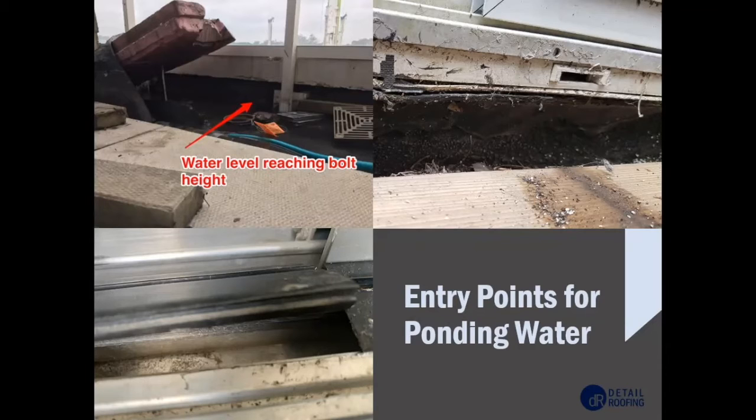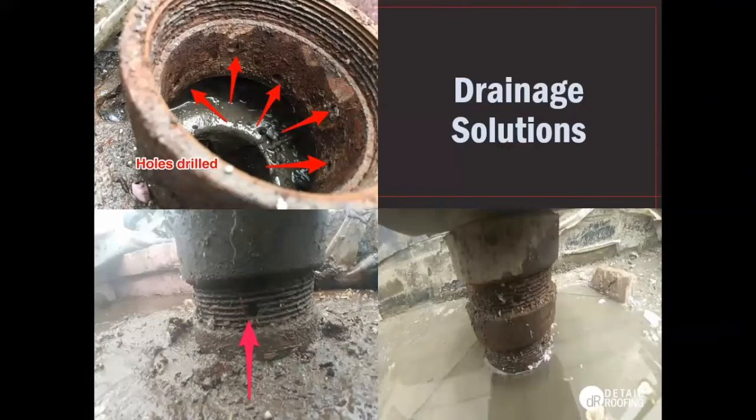Aside from making sure that the drains are clear, there are a few options that can help to encourage adequate drainage on the balcony surfaces. One thing that we see quite commonly on balcony surfaces are these raised bi-level drains.